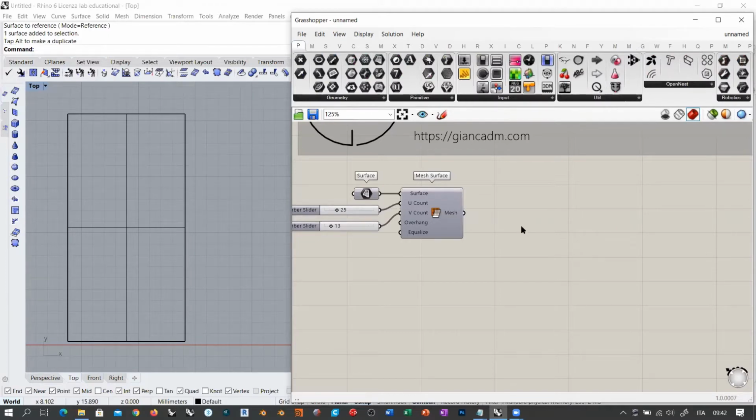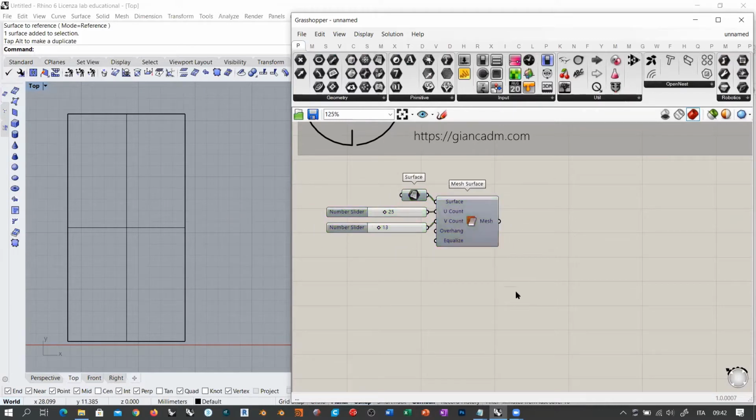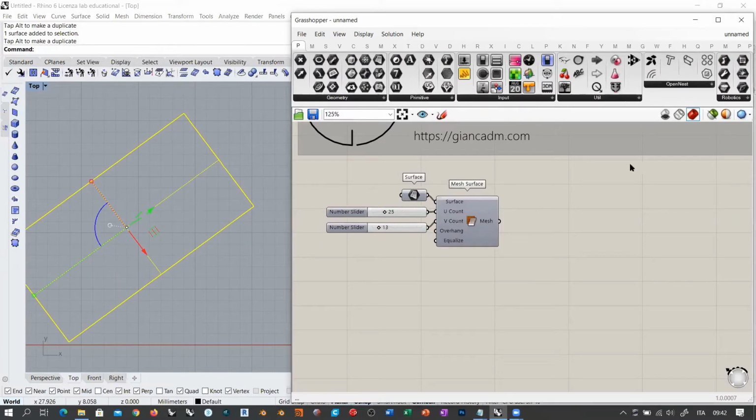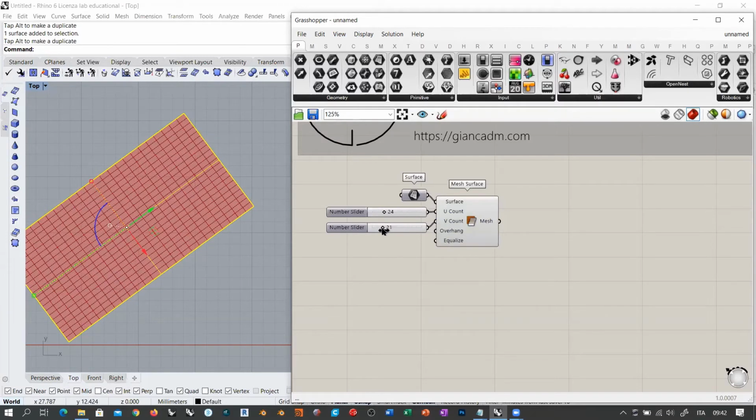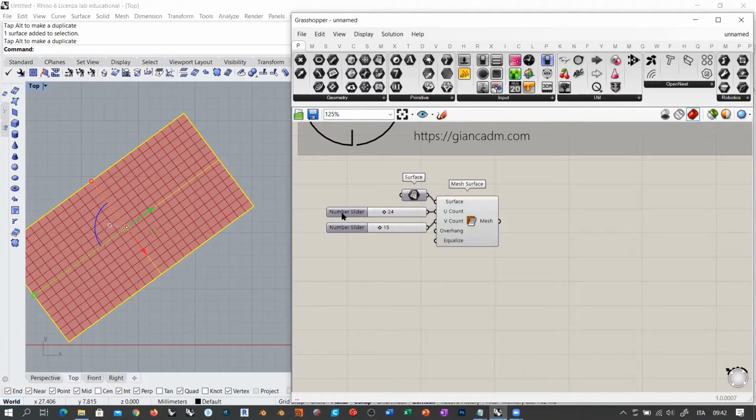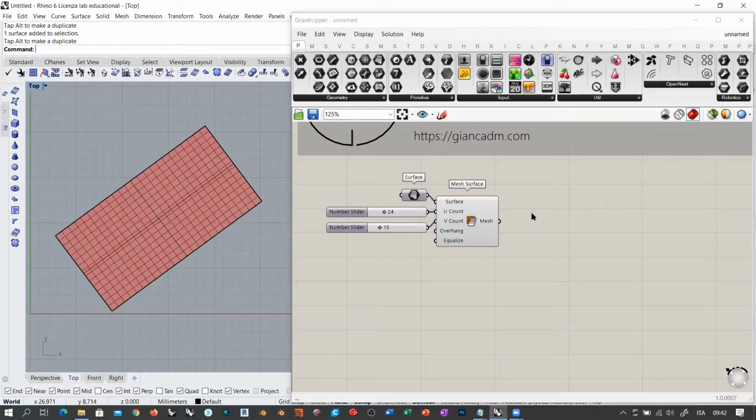workflow. So we can say that the only thing that we can do here in Rhino Grasshopper is obtain some kind of rectangular mesh topology based on the UV direction, of course, but only in two horizontal vertical orientations, independently from the orientation of the mesh or the surface. So even in this case, I always have the horizontal vertical, or let's say longitudinal and cross section direction. So this is mainly the topologic potential that you have in Rhino and Grasshopper for mesh modeling.